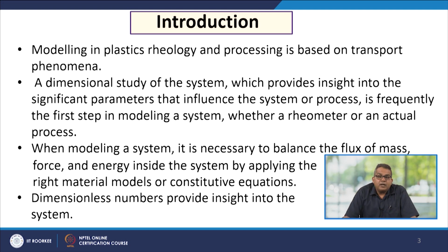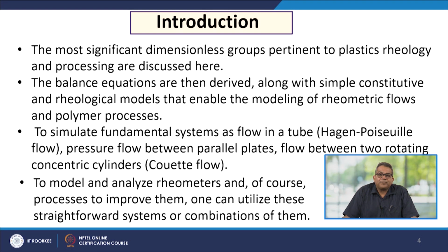So usually a dimensional study of the system, which provides insight into the significant parameters that influence a system or a process, is frequently the first step in modeling a system, whether a rheometer or an actual process. When modeling a system, it is necessary to balance the flux of mass, force and energy inside the system by applying the right material models or constitutive equations, and dimensionless numbers provide insight into the system.